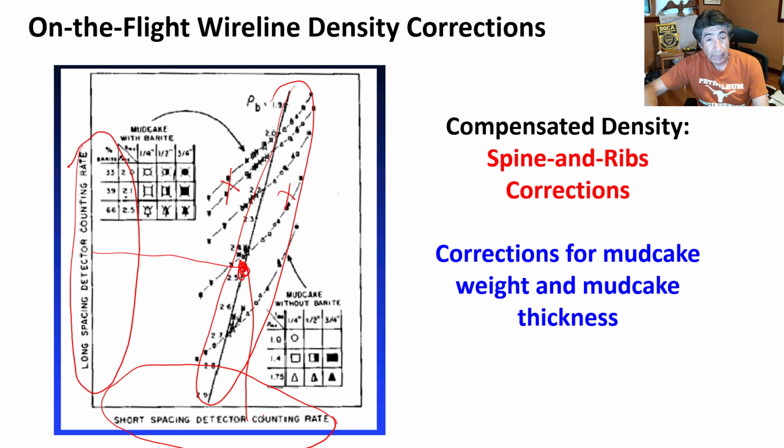And then why isn't that measurement on the calibration guide? Well, the answer is because the sensors are not making proper contact with the formation, or there's some other material that is causing abnormal counts.